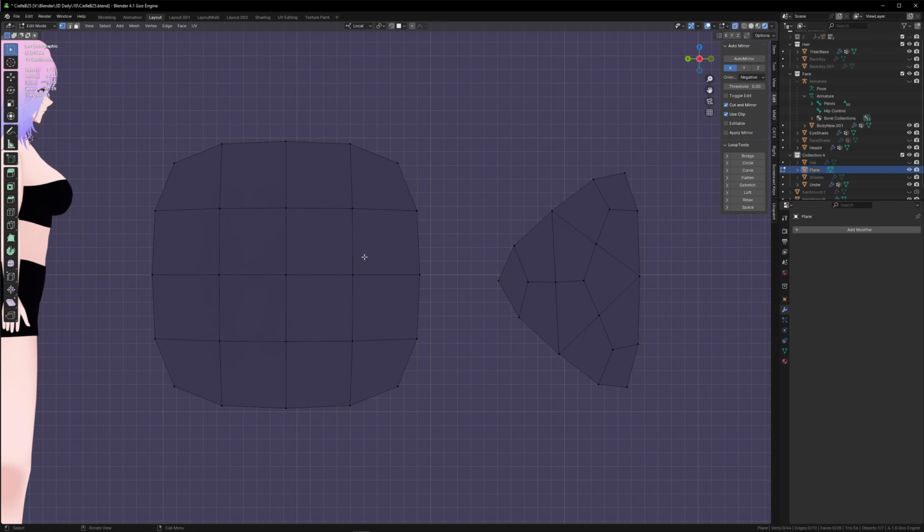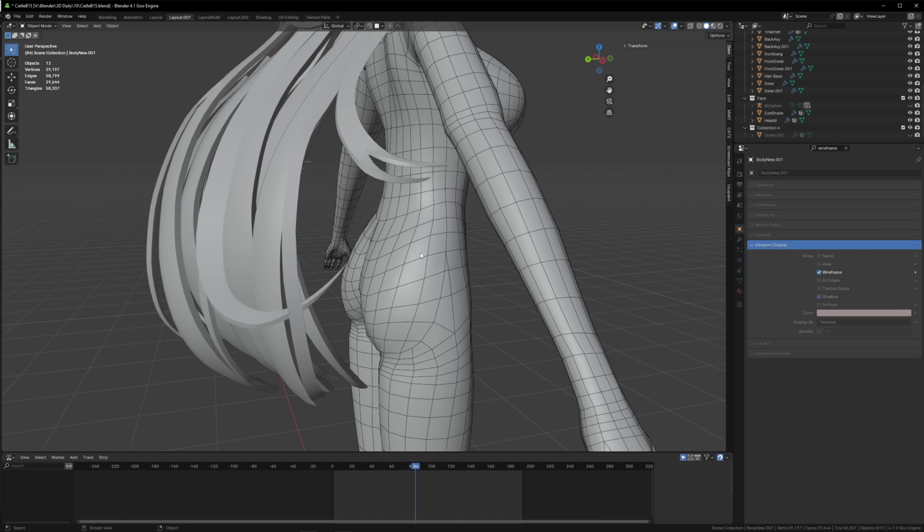But after you've applied the subdiv and you've done all the loop cuts that you need, when you get to your finishing touches, you can start introducing tris to clean up the model and lower your density in certain areas, sometimes by merging, and sometimes you add. So triangles at a certain point are a very useful way to increase or decrease density in areas that you choose. That being said, let's talk about mesh density.